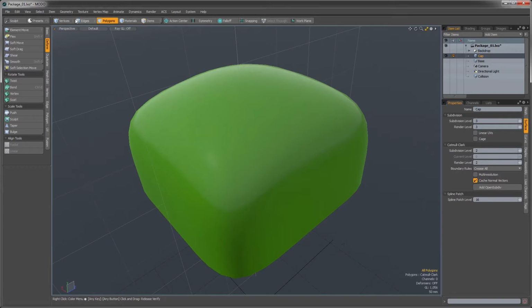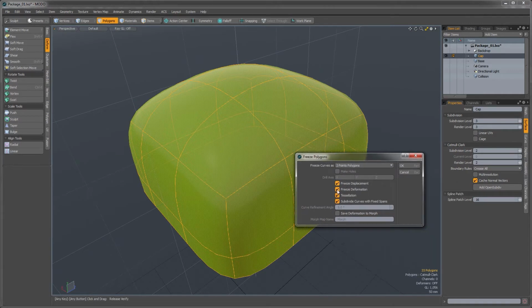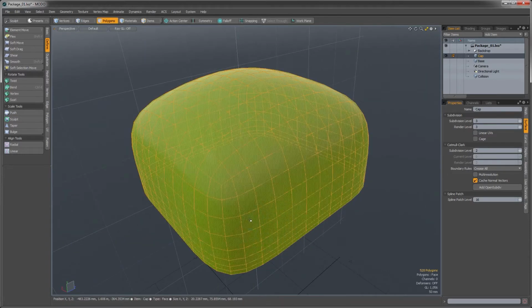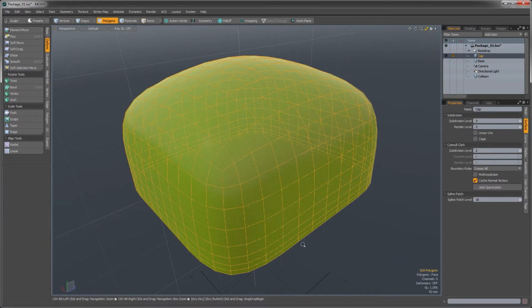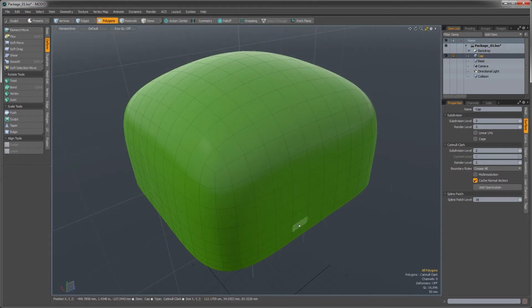Now I'm going to take that, I'm going to just go geometry and freeze. Keep these options there. So now if I turn on, you can see now I've frozen that at this higher level of polygons. So I'm actually going to then turn back on the subdivision. So hit Shift Tab to smooth those guys again. And then I want to set the boundary rules to smooth all.